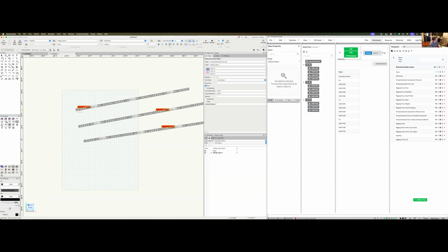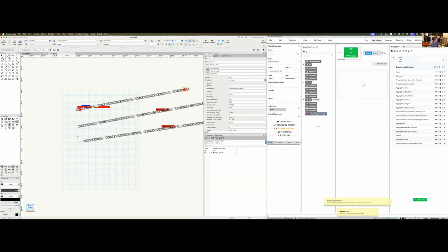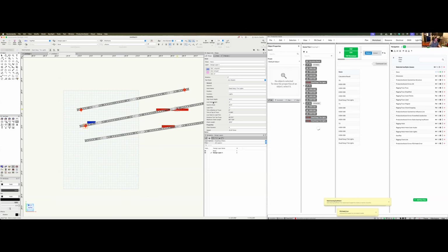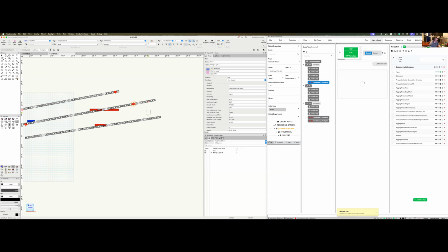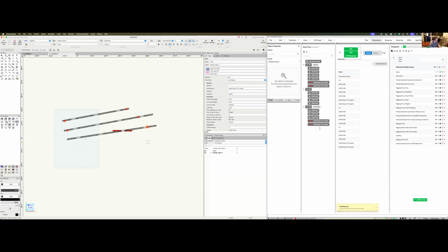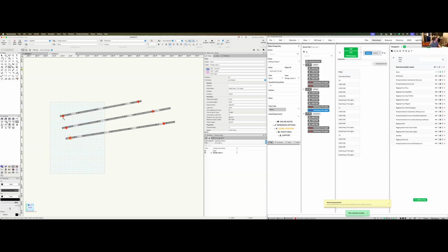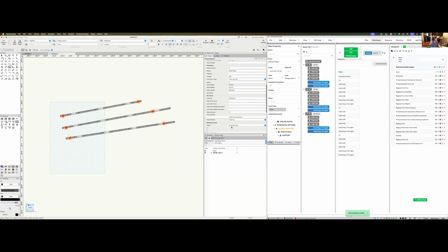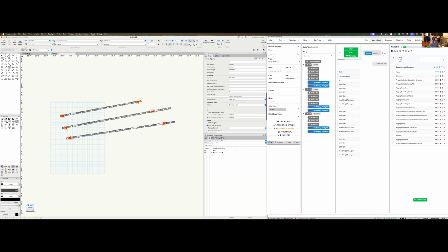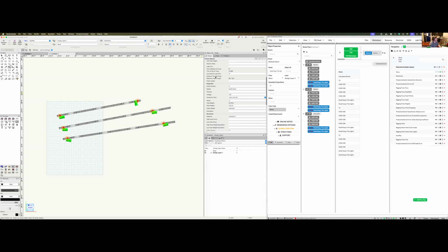Next, add a hoist using the hoist tool. As soon as the hoist is added, Production Assist updates its calculations. Once all necessary hoists are inserted, the error messages disappear, and the system displays accurate load calculations. To view the hoist reaction force, simply select the hoist and enable the Show ID panel. This displays key data such as hoist force and chain shorten values.